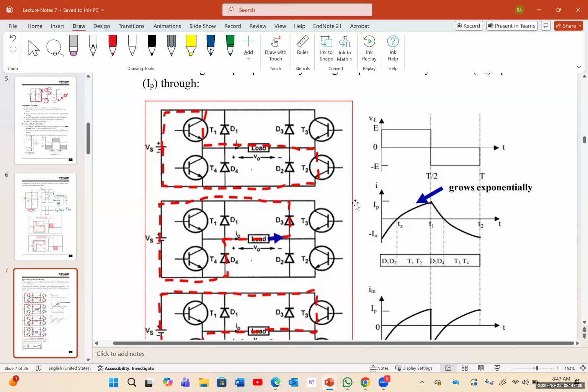almost all of the loads that we have here for an inverter is usually an AC motor, and the AC motor is created from a bunch of wires, which are the stators and the rotor. They have wires that act like an inductor, and that inductor causes a delay in the current. And you're going to have a lagging, for example, power factor.